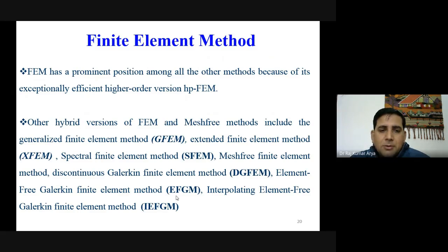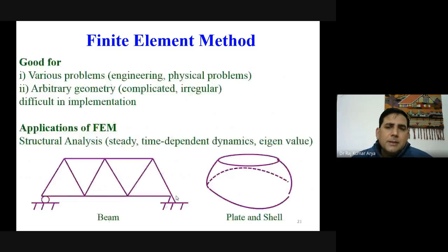So I will talk about the Galerkin finite element method. Here you have an arbitrary geometry and you convert everything into elements. Let's say this is a beam. The entire beam is discretized, and you can see how many elements you have. One element is this, another element is this, and another is practically the rest of the beam. You have divided it into three elements. Fine.